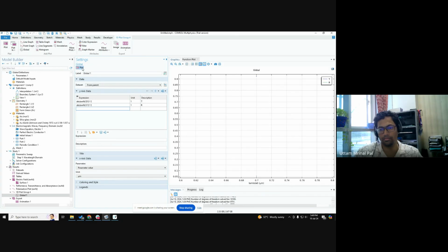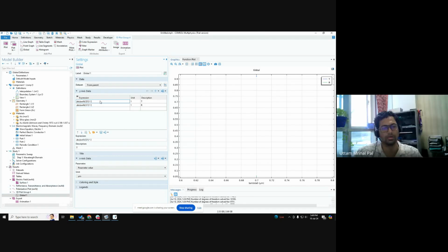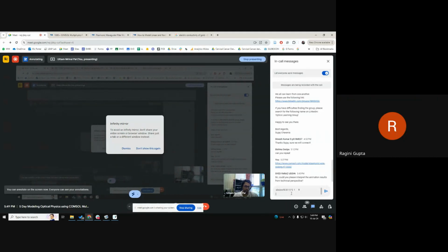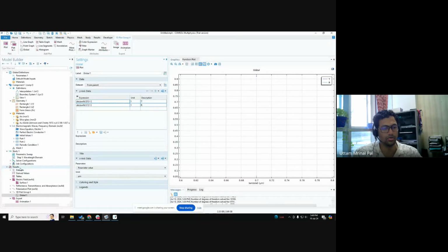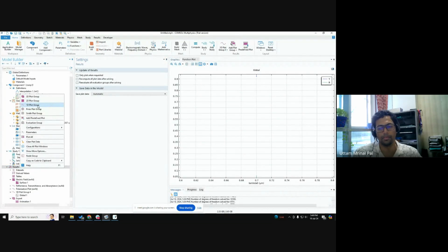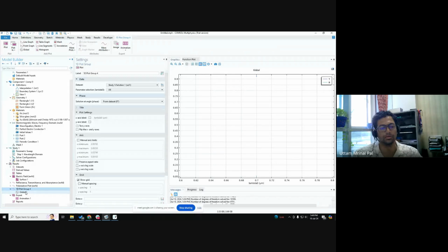Sir, how did you get this 1D plot? Just right click on the results node, and click on 1D plot group.